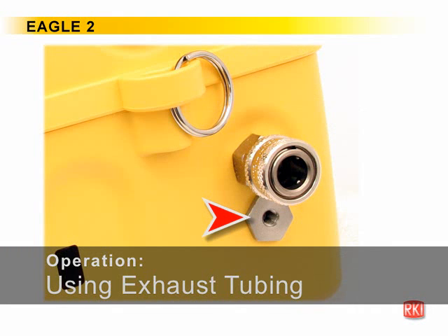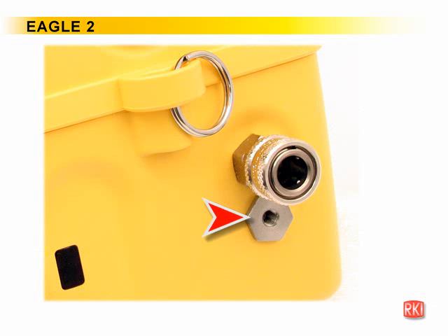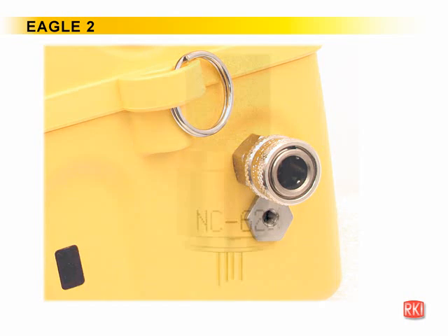The Eagle 2's exhaust fitting has a female 10-32 thread to allow for the installation of a hose barb fitting with a male 10-32 thread to which a flexible exhaust tube can be connected. If you utilize this feature, the tubing used must have a minimum internal diameter of 1/8 inch. RKI recommends using flexible polyurethane tubing with a maximum exhaust tube length of 20 feet.